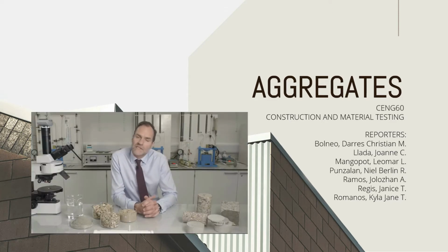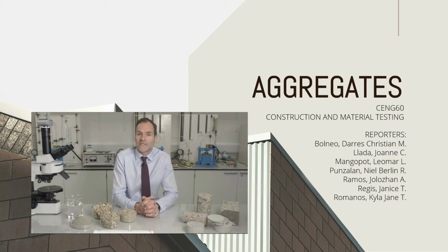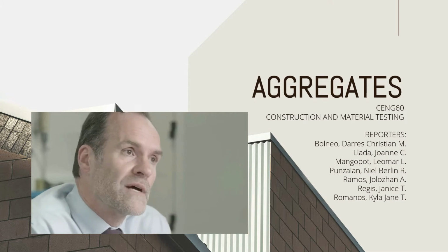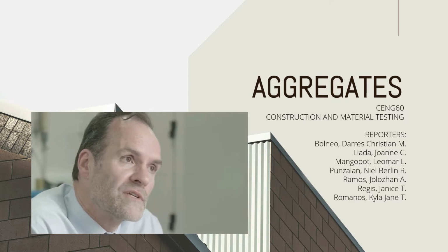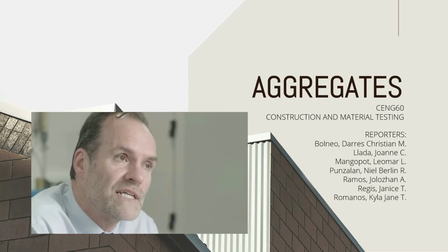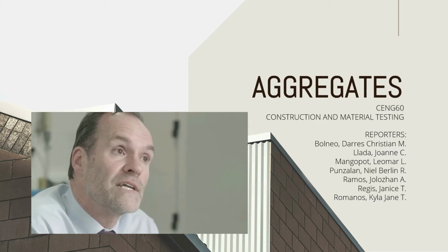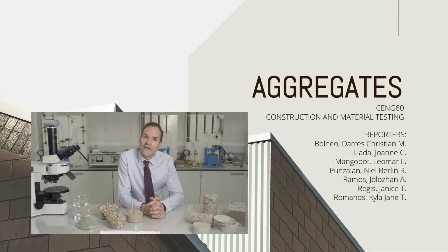Yes, it does. Cement manufacture involves heating the raw materials to a temperature of 1500 degrees C, which uses a lot of energy. Also, as the limestone is broken down in that process, it releases carbon dioxide, leaving calcium oxide. And that CO2 goes into the atmosphere and contributes to the carbon footprint of cement. But actually, that isn't the whole story.